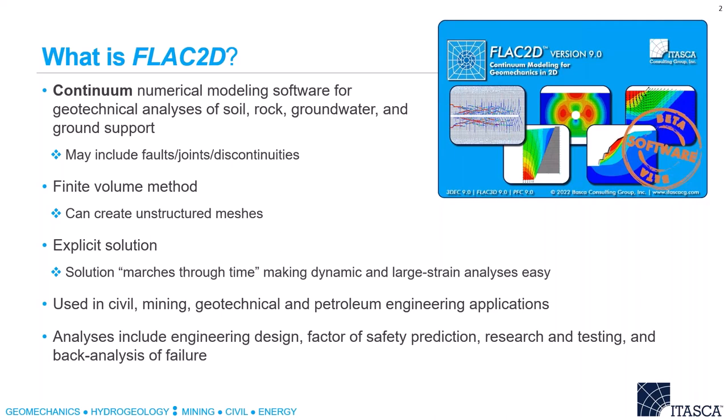What's different from most finite element programs that you may have seen before is that FLAC2D uses an explicit solution. What that means is that it marches through time in a pseudo-dynamic way, and it makes it very easy to do dynamic problems, large strain problems and highly nonlinear problems.